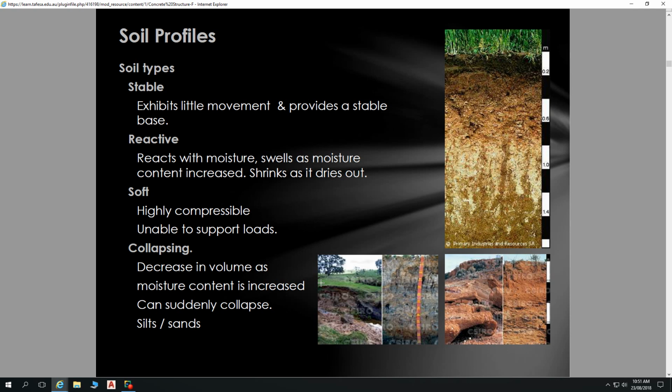A large part of my old job was going around doing laser levels around a building to work out what's happening. I think the biggest difference I ever saw, from one corner of the building to the other corner, was 200 millimeters. But I went around a building that had 150 millimeters of movement and had basically no cracking in it. And yet I've been to other buildings that only exhibit around 30 to 40 millimeters of difference and have significant amounts of cracking.